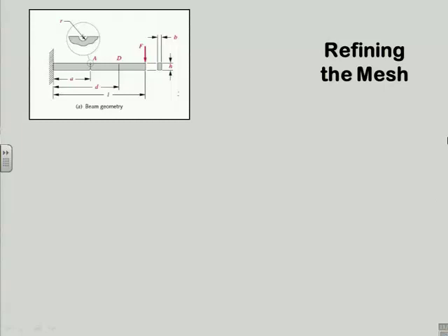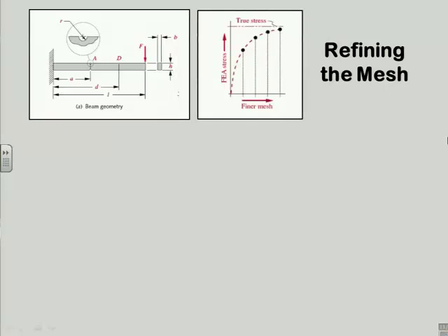So let's talk about getting the mesh right, which, again, is somewhat easy nowadays because of these automatic meshes. In the bad old days, you had to go in and create that mesh by giving it the XY or XYZ coordinates of every node of all these elements, which is a nightmare. But thankfully, that's behind us. So here, right out of Chapter 8 in your book, I take a very simple problem, a cantilever beam. I stick a notch in it to make things interesting. And I put a load on the end, and I make it rectangular in cross-section, so it's very simple to calculate. Because what I'm doing here is I want to have a test case that I can solve by hand.